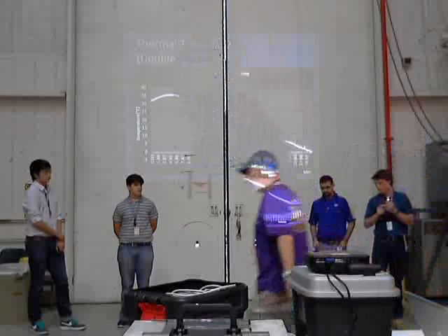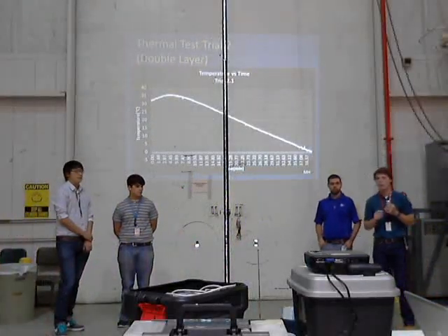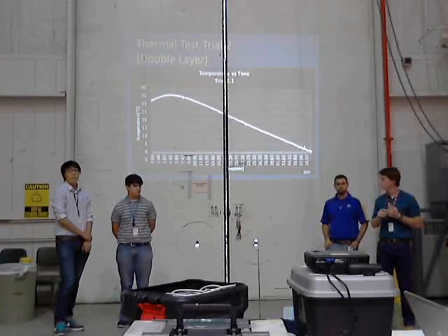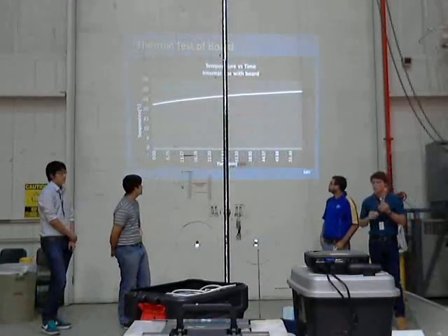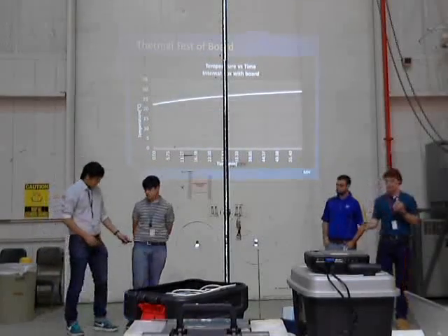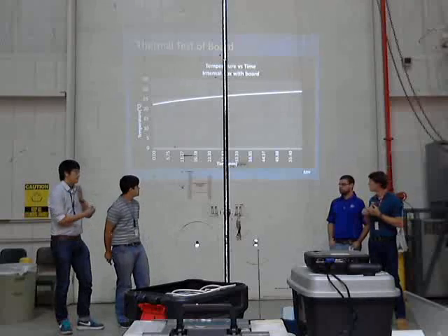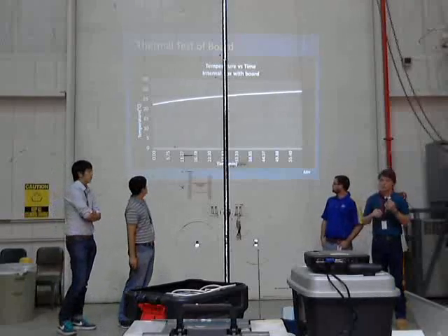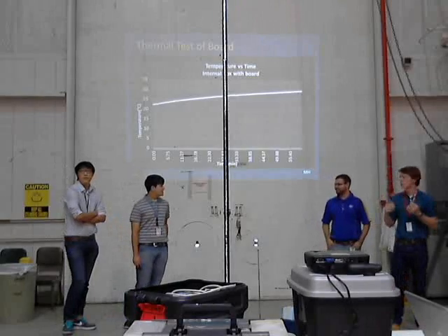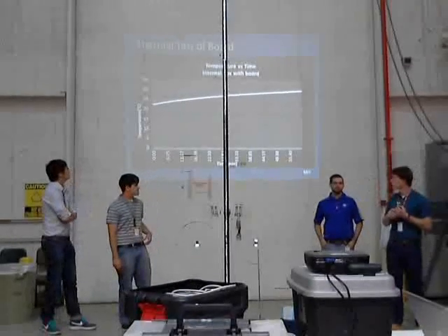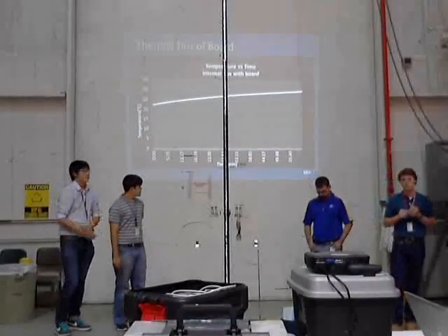So here we decided to give us a safety buffer, and we put 3 layers and we made the layers a little bit thicker. And then we will also have the temperature rising due to the actual board. And we did a test there. We put the board and we ran it for about an hour with the Logger Pro temperature sensor in there, and we saw that it raised about 8 degrees just from the board being placed in there by itself.